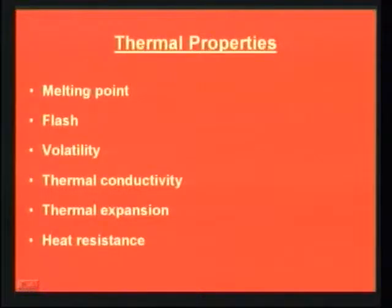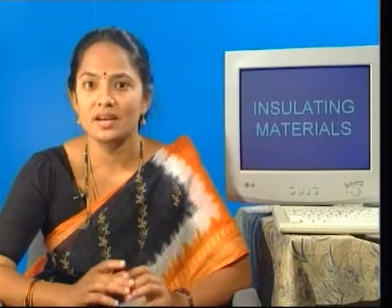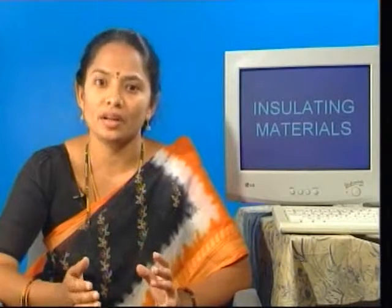Right. We will look into each of these in detail. Melting point. The melting point of liquid dielectric used in solids should be sufficiently high. Melting point is important in specific cases like non-draining compound paper insulated cable. It is desired that in the entire operating range of cables, the impregnated compound must not melt.